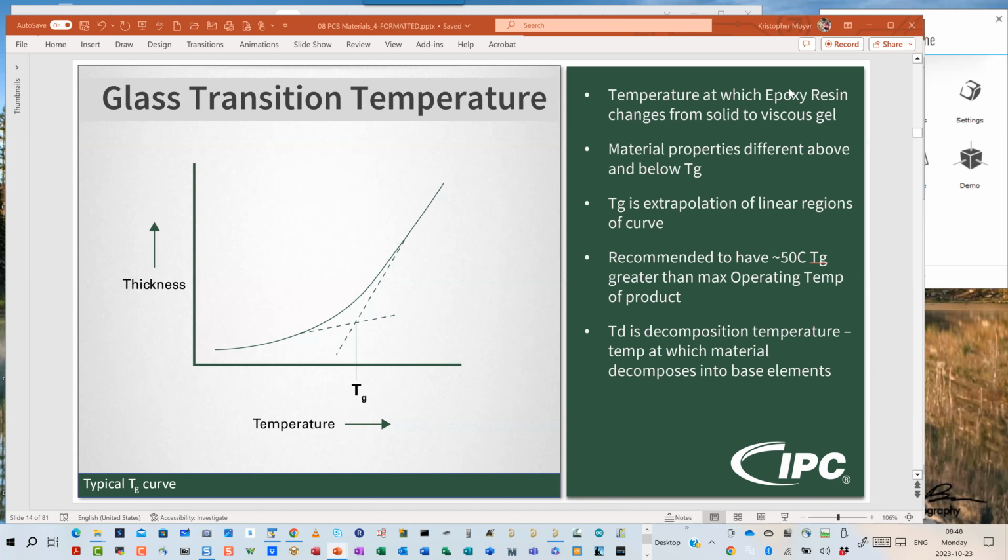No, so the reason why I ask is because we often need to do, let's say, HALT boards or HAST boards where, if the device needs to work up to 125, we need to heat it up to 175 to test some things. And then I'm really wondering which material we should be choosing, and if we are choosing something which has a T sub G of around 175, if it is just a matter of mechanical stability, or if it also would change what we have with reflections, because we often have relatively high clock signals and stuff like that. So HALT and HAST, your accelerated life stressing and stress screening, right?